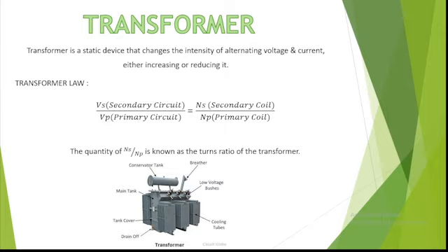Transformer. Before we learn about transformers, I would like to share why this topic is important in radiology. In the high voltage circuit of an X-ray generator, step-up transformers are used to convert the main voltages, which range from about 120 to 240 volts, to the high voltages, which range from 20,000 to 150,000 volts, required for X-ray production. It also transfers electrical energy from one circuit to another by mutual electromagnetic induction.